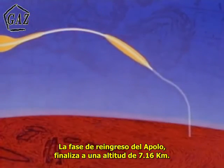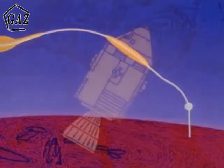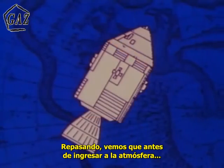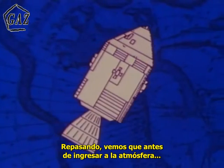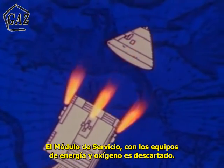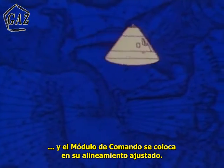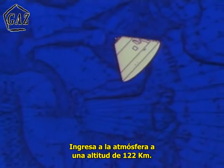The Apollo entry phase will terminate at about 23,500 feet altitude. At this altitude, the drogue chutes will come out, and the spacecraft will descend to splash down by parachute. Reviewing now, we see that before entering the atmosphere, the service module containing all but the entry oxygen and power supplies will be jettisoned, and the command module positioned in its trim alignment. It enters the atmosphere at the 400,000-foot level.